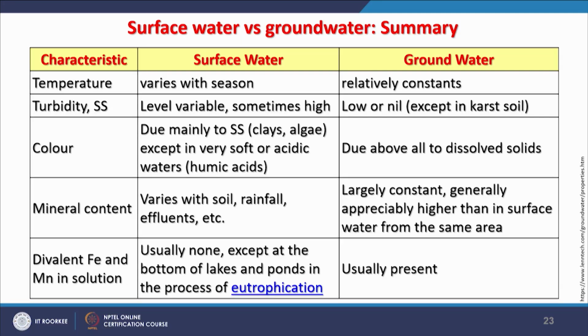Why low? Because in case of over-exploitation of groundwater, there might be some turbidity in subsurface conditions. So, when water comes on the surface, it might have some small suspended particles in it. Of course, when turbidity changes, color changes, and there might be some organic components like algae or sediment components like clays, and they change the color.